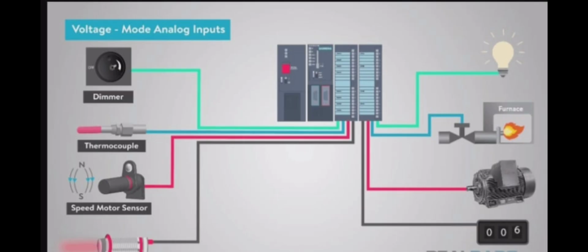That means it gets the output from the field via these sensors like analyzer, transmitter over the 3 core or 2 core cable. It means the 4 to 20 signal comes from the field devices, as I mentioned earlier, like PT, TT, that is pressure transmitter, temperature transmitter. It directly goes through a 3 core or 2 core cable to TB, that is terminals, to the AI card, in the form of 4 to 20 milliampere.